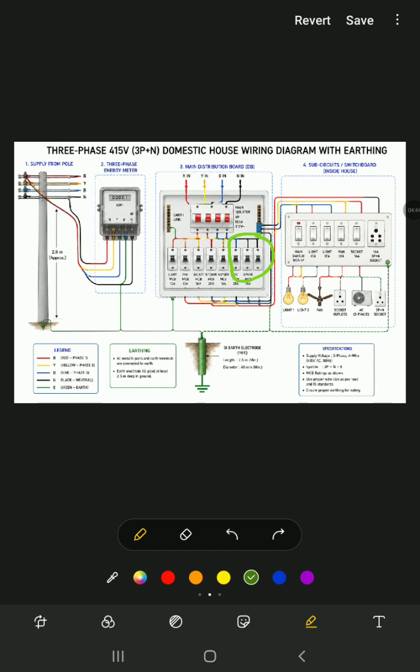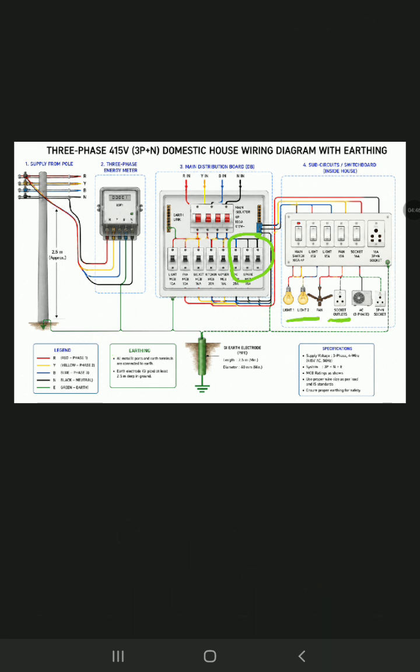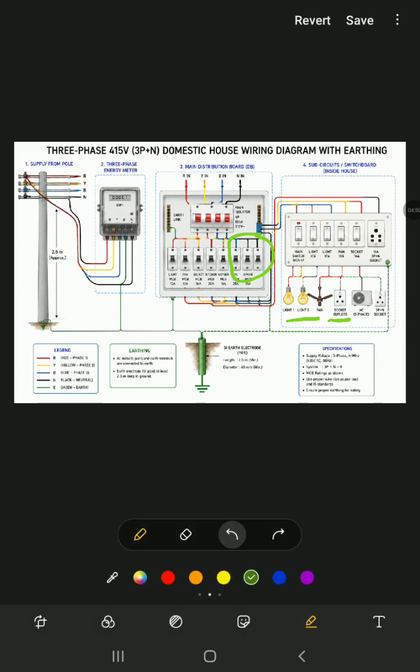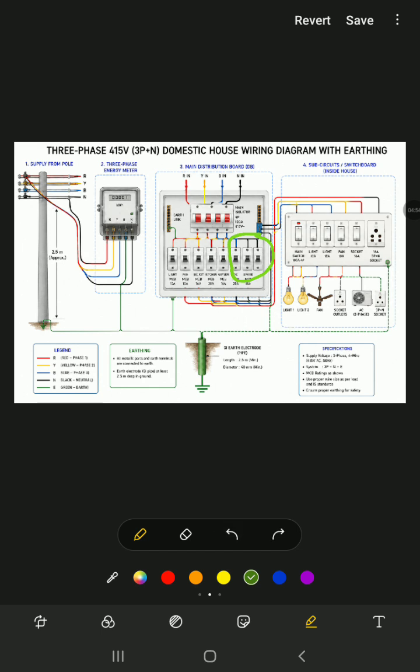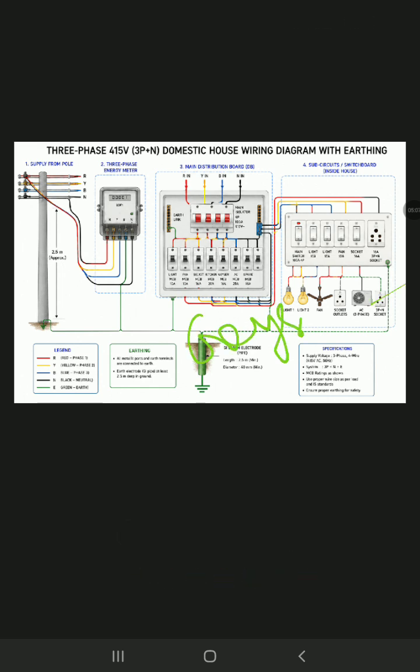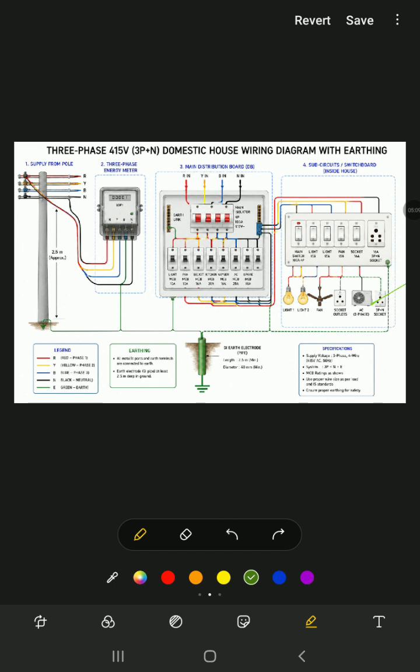For example, a bulb, a fan or a normal socket takes only 6 amps, not more. We can use light appliances like light, fan, hair dryer, laptop charging, computers, desktop speaker, etc. But the appliances which need 16 amps current are AC, geyser, heater, iron boxes, high power amplifiers, etc.